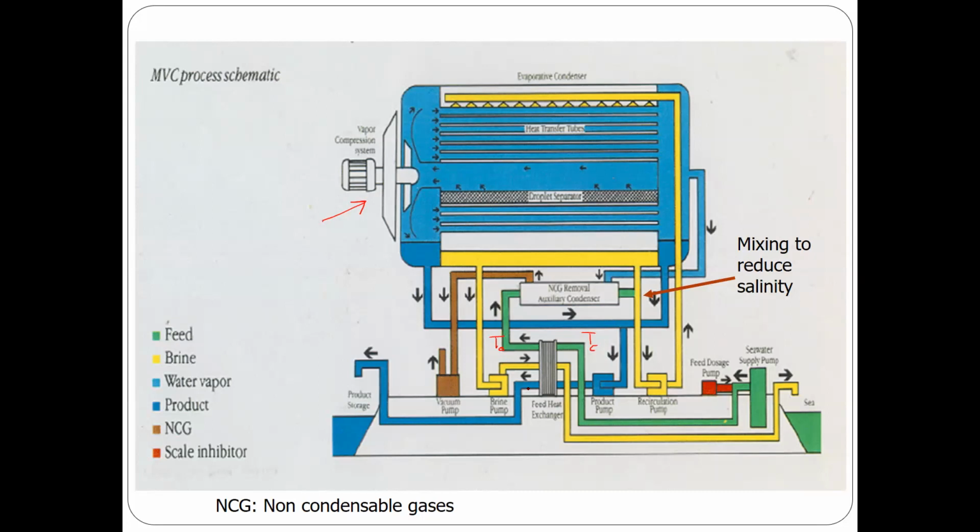So here it's not necessarily a single heat exchanger. Actually, in our analysis we are going to do it as if they are two heat exchangers. One of them is between part of the seawater and the brine, the other is the rest of the seawater with the distillate. So this is not necessarily the only alternative for the preheating of the feed.